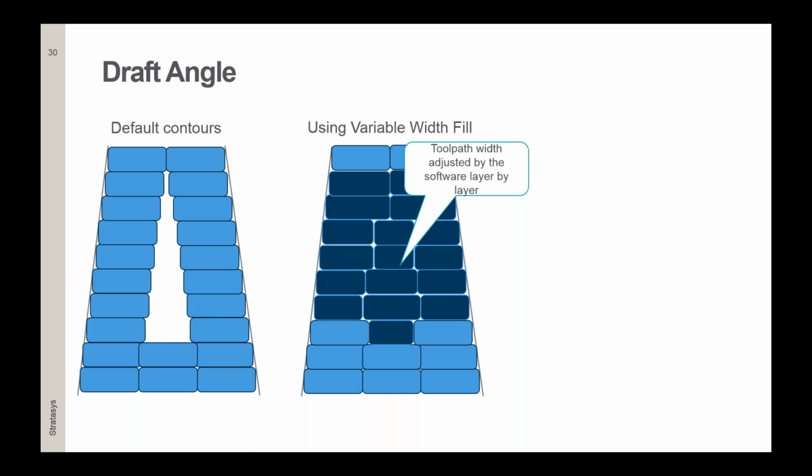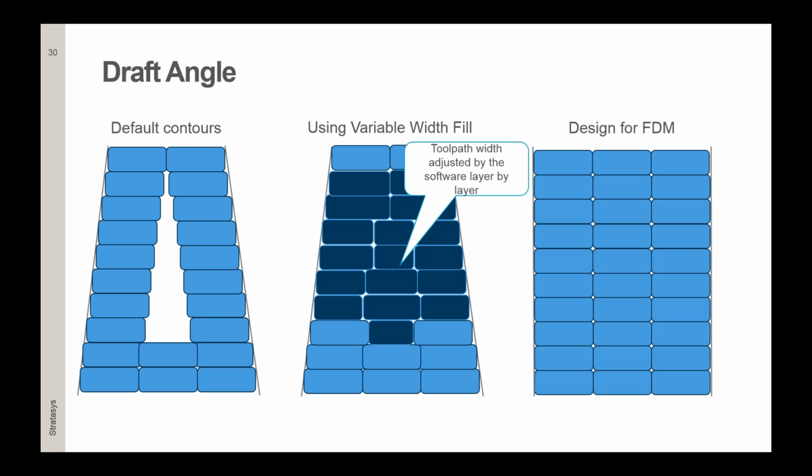However, if you are working in the aerospace industry, rail industry, or basically any industry which requires certifications, and by certifying the parts which will be built into planes, trains, or also cars, most likely you will have to print the part using the default options. Using something variable will not fit for certification. So this is also an additional step for the operator, checking the part to see if all the gaps are filled. So it is usually better to apply the rules we have learned to have consistency on your parts.